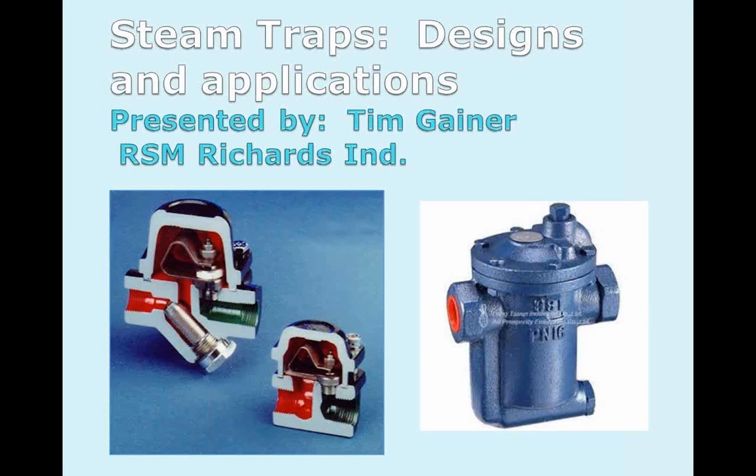So you've got the steam in there, and instead of it venting out and then condensing around it, and again, I'm making assumptions with this, but even if it's trapped in the bucket and you don't have that vent, it's going to condense. The trap should not be insulated, so if nothing else, the outside air should be cooling the trap, and eventually any condensate in the bottom from the prime is going to help that steam condense in there. So I'm making an assumption, because I've not seen that, but you're still going to end up having that steam condense, and the trap will open.